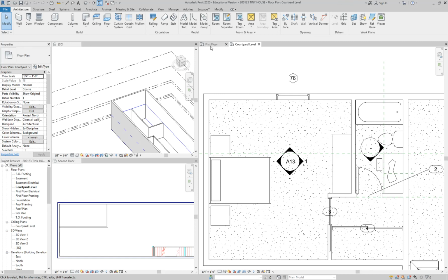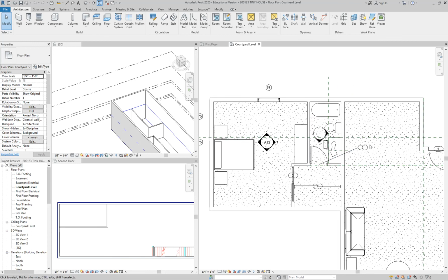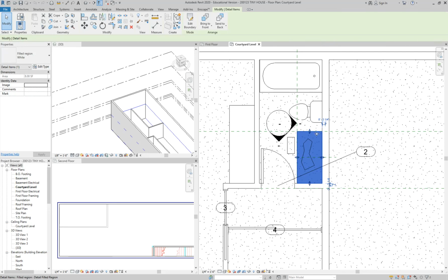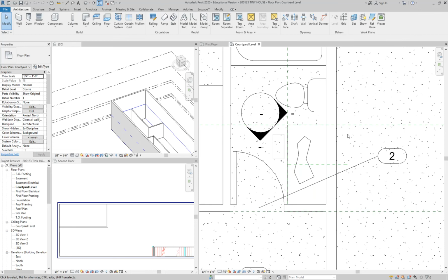Okay, I have one more question. On my kitchen views and my bathroom views, I drafted in countertops. But on the floor plan, things that went over the countertops, like upper cabinets, messed up. I expected the upper cabinets to block part of my countertop that I drafted, but it wouldn't, because it's over the cut line. So I would do a solid region to cover it up. But then I wasn't sure, should I pull the countertop underneath where it would really be, or only pull it to the front of the upper cabinet?